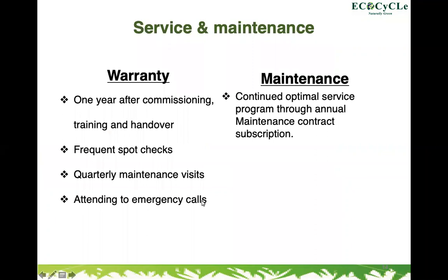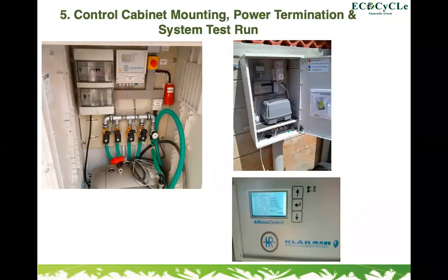One more thing you should note in our control cabinet is that we have a float switch. You can't see it from there, but that's one. The float switch is responsible for ensuring the correct level of sewage is treated at a given time. But apart from the float switch, we have the PLC that is also responsible for attaining the correct level. That's all about the control cabinet. From the video you saw, it's mounted on the ground. It depends on the site. Sometimes it can be mounted on the ground, sometimes on the wall, depending on the size of the system.